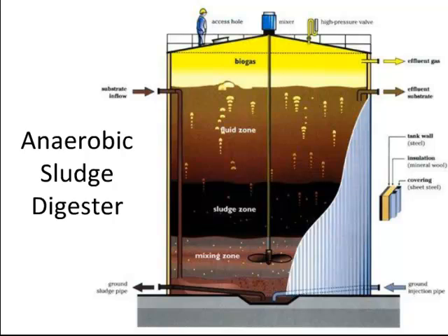So you can make electricity to turn the mixer to drive the sewage treatment plant. If it's burned efficiently, it can also run the lights and the computers and all the other equipment at the sewage treatment plant. And if it's a plant for a large city, it can even generate electricity for that city. Portland, Oregon has anaerobic digesters that generate large amounts of methane, and that methane goes into a fuel cell that produces electricity for homes within the city.